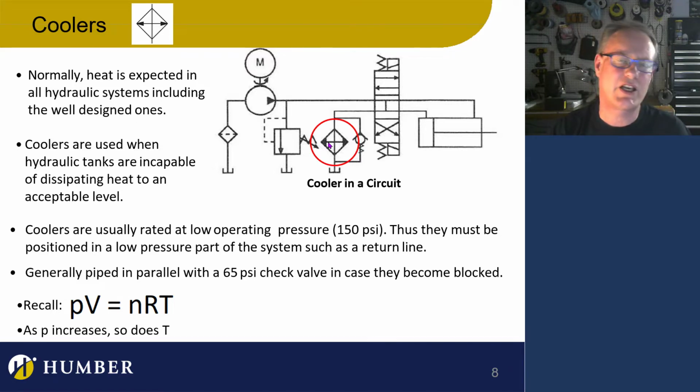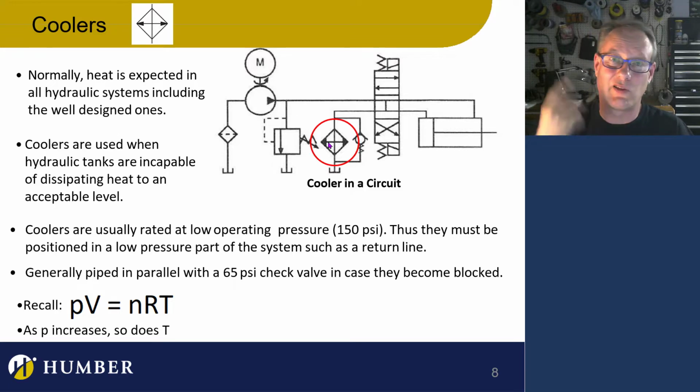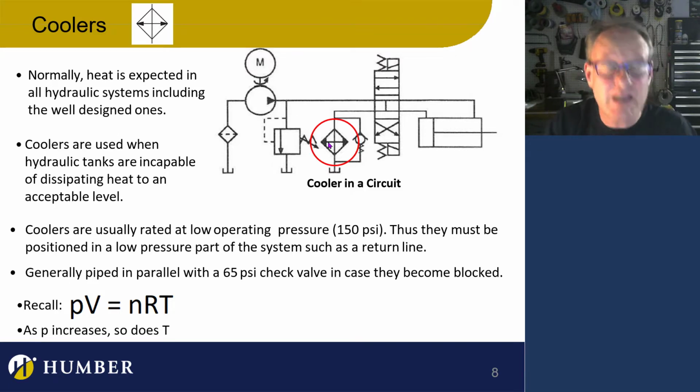It's all about application. It's all about, hey, is the pump burning out? Not the pump, pardon me. Is the DCV burning out? Is there a motor being used and it's burning out? You have to understand that heat is a real problem in a hydraulic system, and sometimes it'll actually damage components. I think the largest thing we will talk about is contaminants. That's the biggest deal about what blows all hydraulic components. But heat is really a big deal.